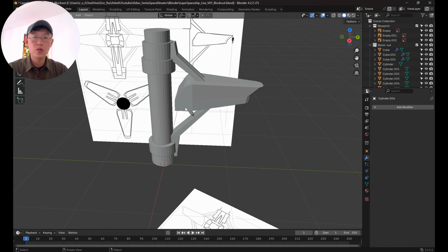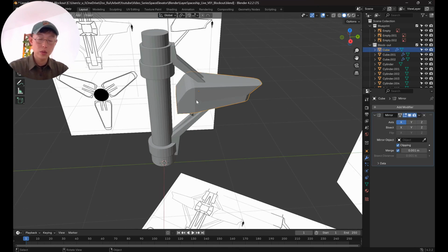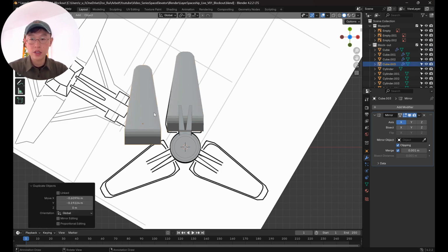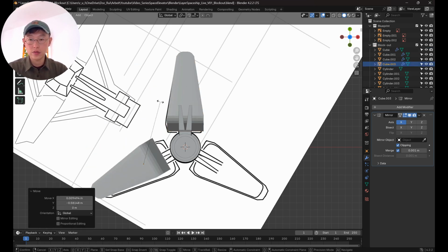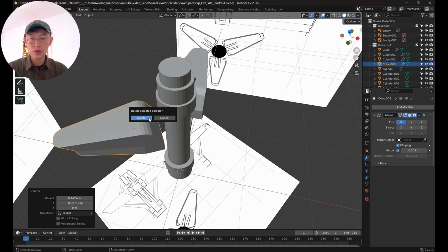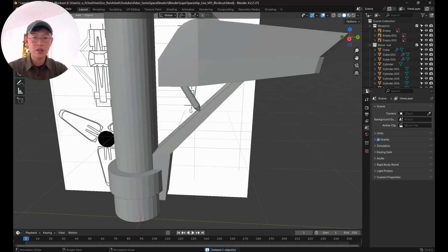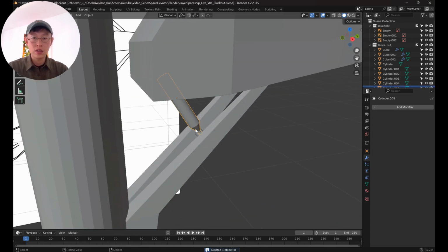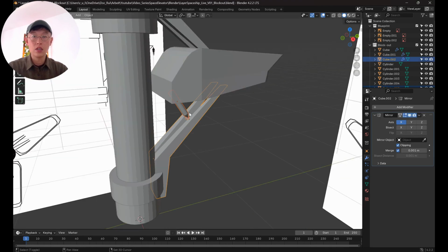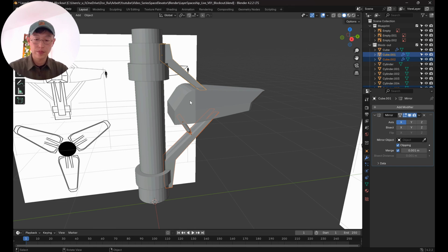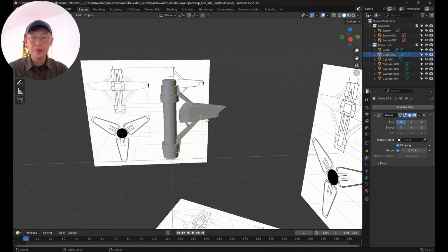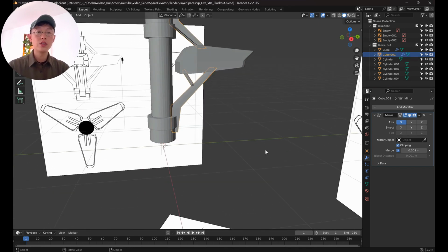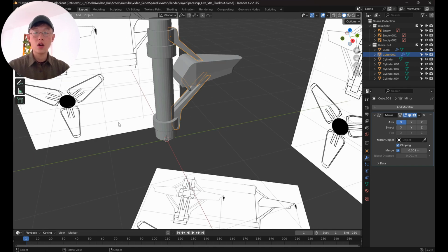So we already finished one side and now we can copy paste it, but I don't want to do it that way, right? You do Shift D and then you kind of eyeball and put it in the right position. It's not very precise and maybe it's not the easiest way to do that. So let me connect all these parts by clicking Control J, and that's already kind of one part. And if I want to array this along the column, we're gonna use now the modify array to do that.